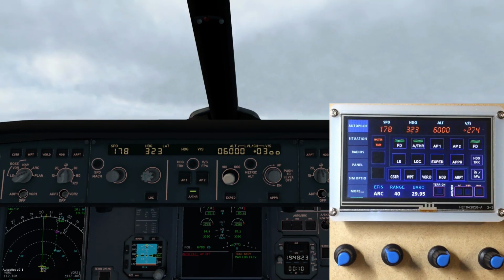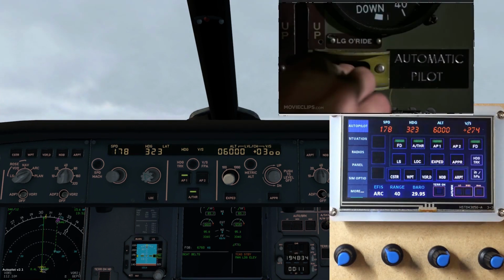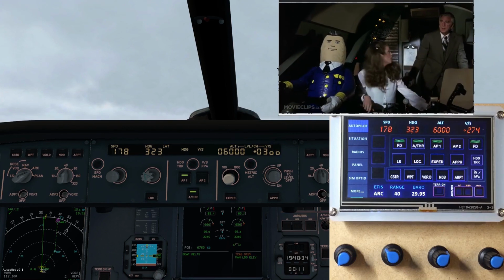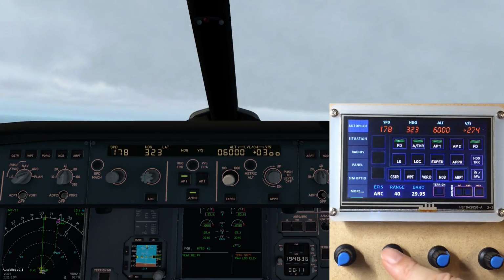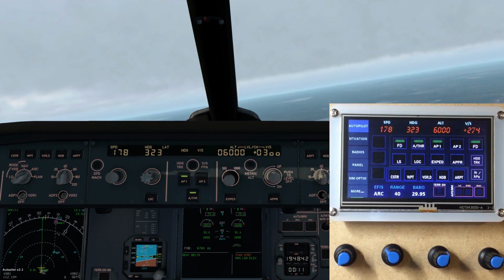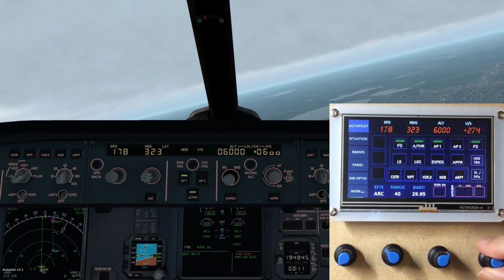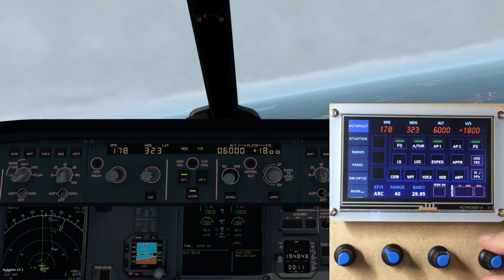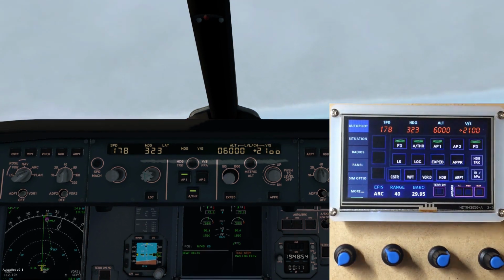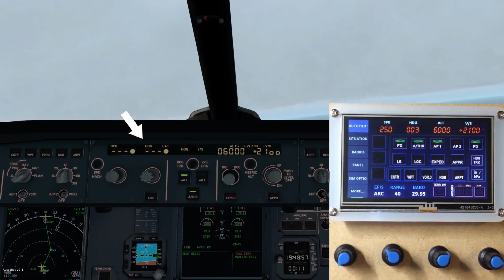We have started things off with a greeting from the master warning. Let's use our touch panel to clear it. Let's allow the autopilot to take over. The four push buttons are used to get in and out of the flight mode. Holding the button down for more than 6/10 of a second will get you into the selected mode. Obviously, the rotary encoders are assigned to program the four parameters on the top row. A short press of the button engages the managed mode.